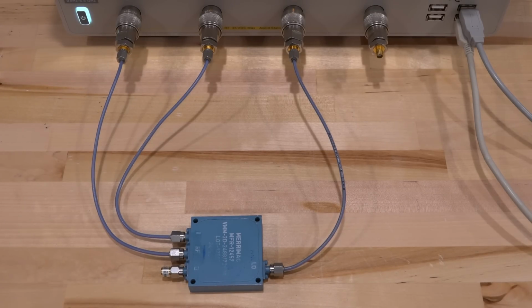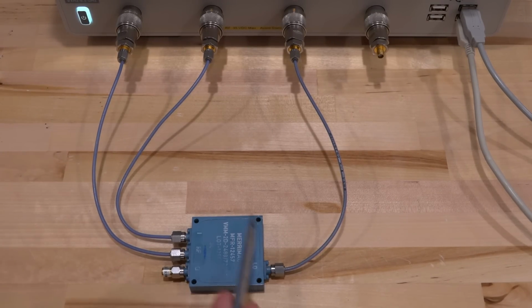Finally, we can measure our mixer, and this is the mixer that I want to measure. Now this is interestingly an IQ mixer, so it has two IF output ports, an I and a Q, which are quadrature with respect to each other. And I'm interested in comparing the two of them and seeing how well their amplitudes match.